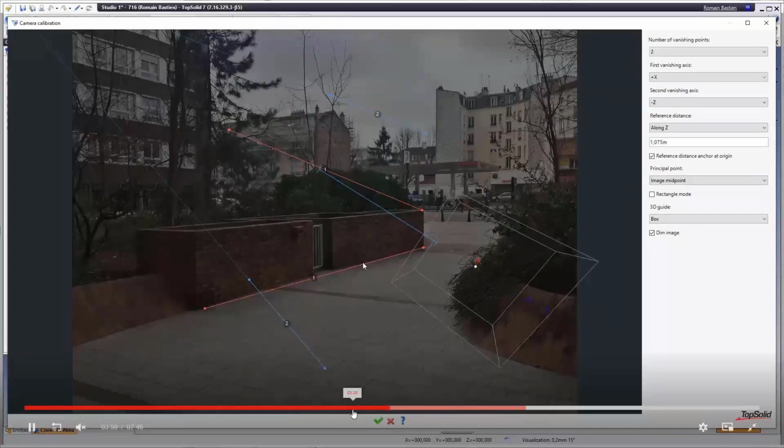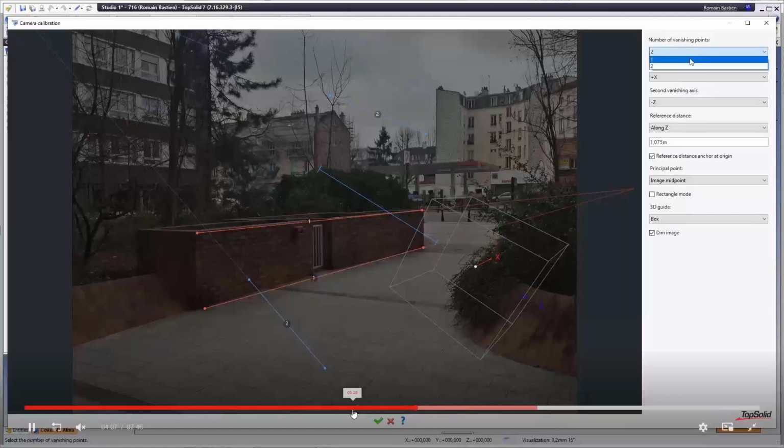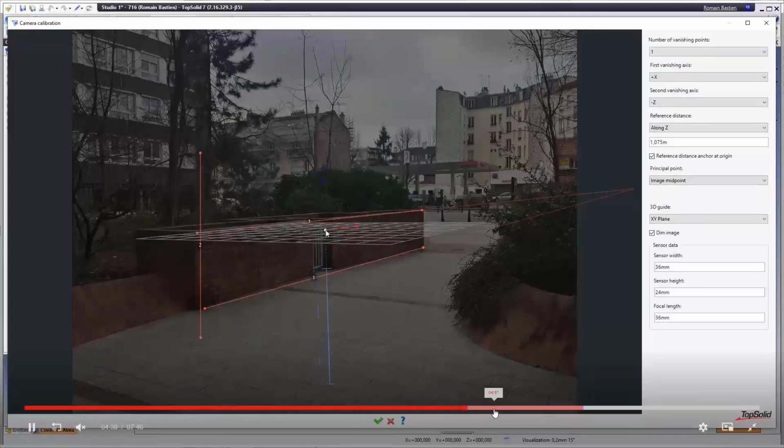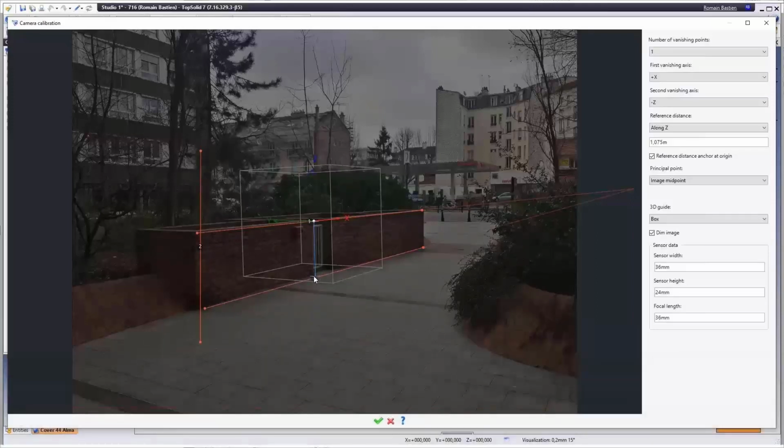You can see that wall isn't so square, but it's not so important. Okay, we're going to define a second one up at the top. Again, it just helps to align things because this photo has perspective, so we have to take into consideration the perspective. Then we're going to align the next axis, and again, I'll fast forward just a little bit here. Then we're going to set where we want the zero to be. So again, we're keeping in mind that this zero is our zero reference in TopSolid. Okay. Then we're setting our scale.